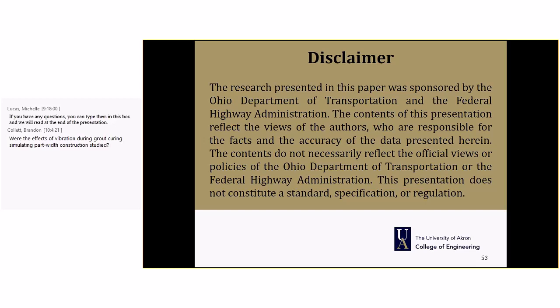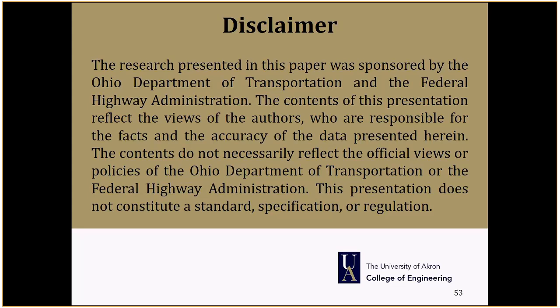So are we wasting money with membrane? Well, in that particular case, yeah, I would say so. How would that be different than any other bridge we put up? I mean, that's pretty standard practice. Well, paving over it like that, is that the same stuff? All I can say is that at least part of the problem is workmanship and the lack of attention to damaging the membrane during the paving operation.